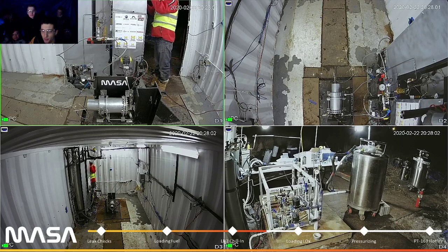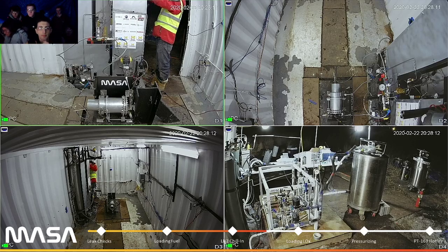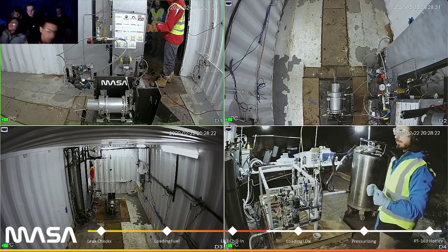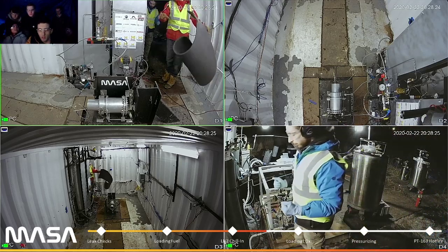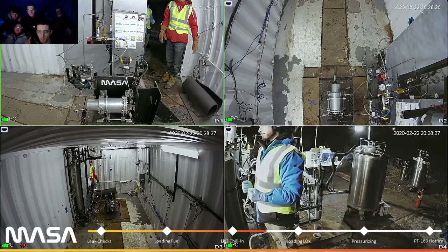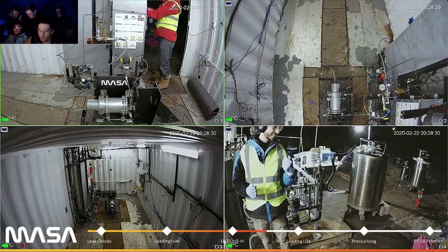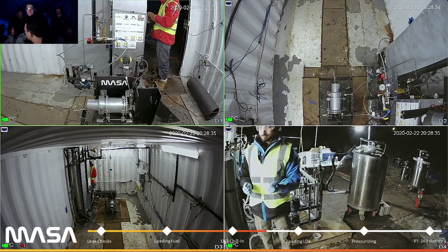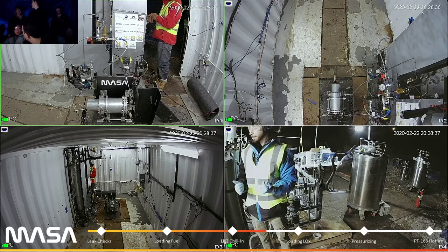The way we have our engine sequence set up, the engine doesn't explode on a hard start condition because we have an extremely powerful igniter. I'm talking about 200 to 300 grams of APCP that we light off. There are about a dozen, maybe two dozen small holes drilled through the APCP so that you get really good surface area across the entire puck, and we ignite it with I think 4 E-matches. So we have a really powerful flame from our igniter.